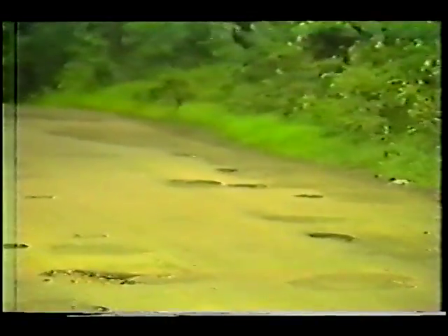The pavement surface must be repaired as soon as the cracks can easily be seen, because water can pass through the cracks, causing more damage to the road base. If the work is delayed, the pavement will become badly broken up and will require major repair.